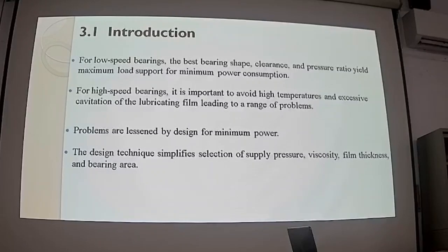The viscosity is generally determined by your motion speed. The lower the viscosity, the easier it can move. The lower the viscosity, the faster speed it can move at. So depending on the operational speed of your bearing, that will decide which kind of viscosity you can choose.